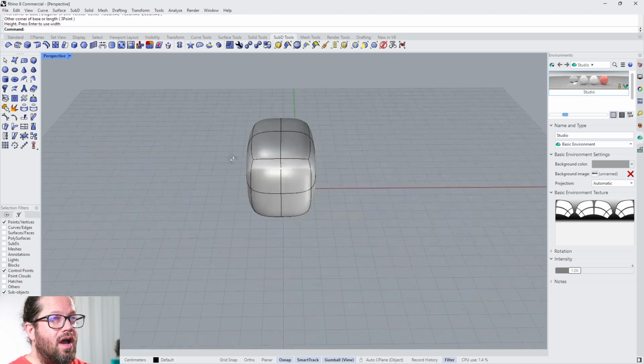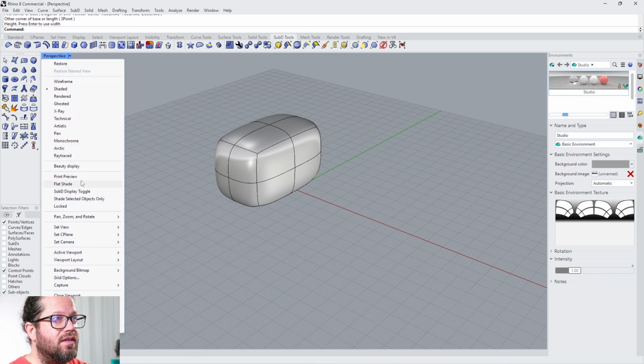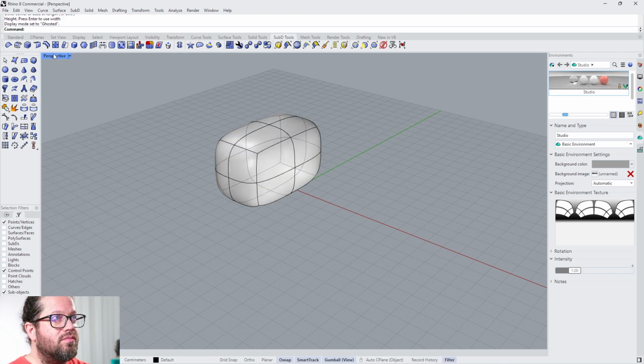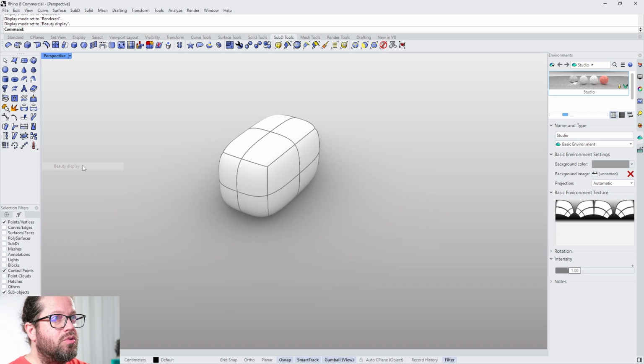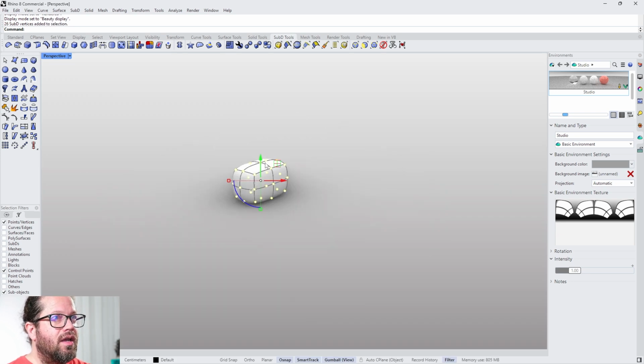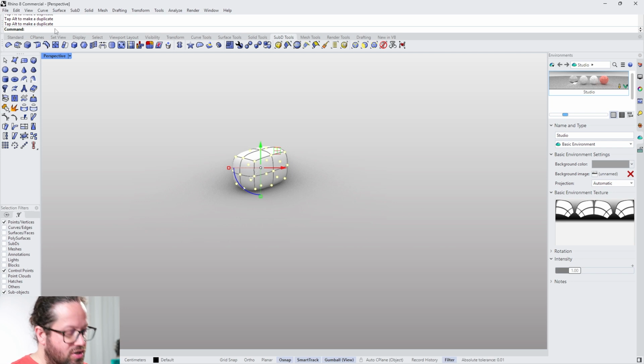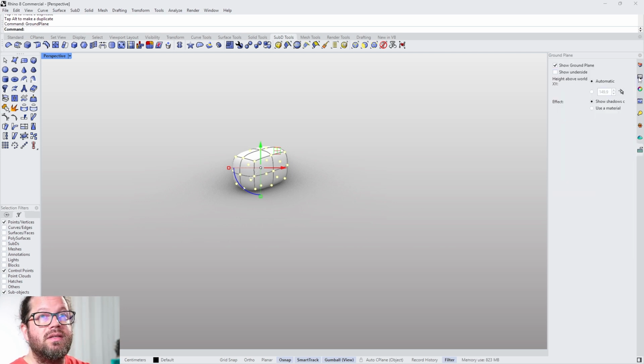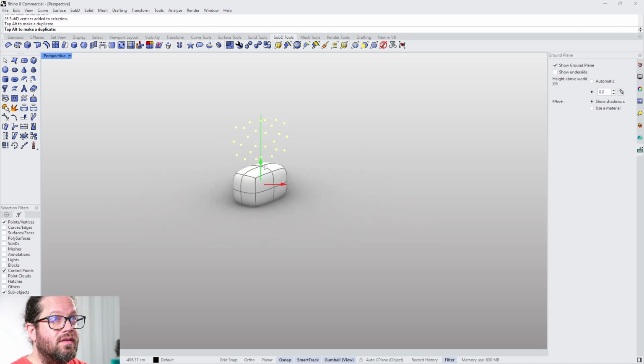Now, I changed my viewport settings a bit. So the normal render settings would be like this, and my beautified version is this one. This is what I normally use, and we will modify this a bit, because what I don't like is that the ground plane is moving along. So we could change the ground plane here, and make it in a way that it's not moving. Just put 0 here. That's it. Now my object can fly basically if I wanted to.